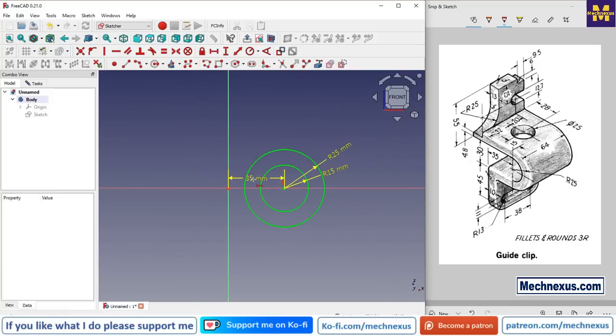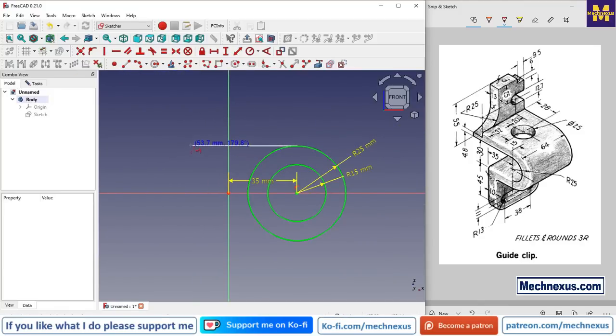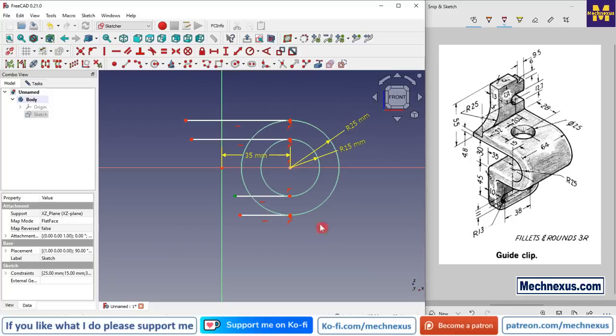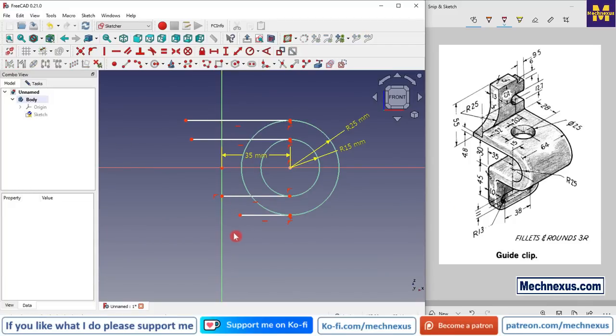And now I will select the line tool, and I will draw the tangent line at the top and the bottom. And now I will keep this edge on my axis, so I will select the axis and this point and add the coincident constraint.